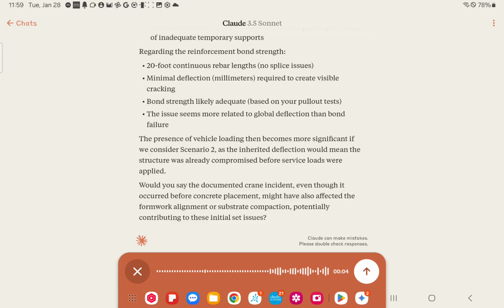Yeah, one more thing then. I didn't do the pull-out test there. I'm just giving you data that I do pull-out test, so I understand how rebar and the bond strength of concrete matters. And the size, of course, and your stone and aggregate all matter also. The greater your bond strength to the rebar, of course, the higher the pull-out test result will be, including breaking the tensile strength, breaking the rebar, fracturing it.